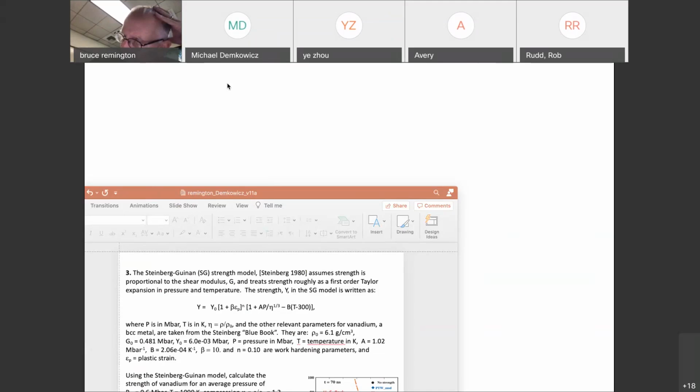All right, maybe I'll take a first stab at that, and Bruce can chime in. So the dislocation density, of course, we don't have any direct measure of either the density of dislocations or point defects at these conditions. It's not something that anyone has figured out a way of determining yet. Hopefully at some point in the future, in situ diffraction can be used through broadening of diffraction peaks to get at defect densities. But we're not there yet, especially in the context of these Rayleigh-Taylor experiments.